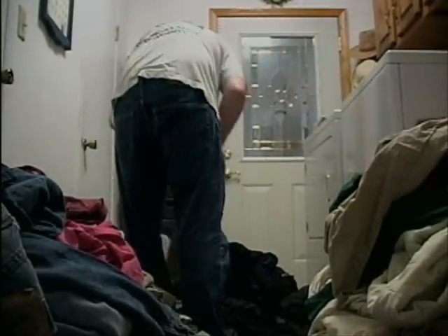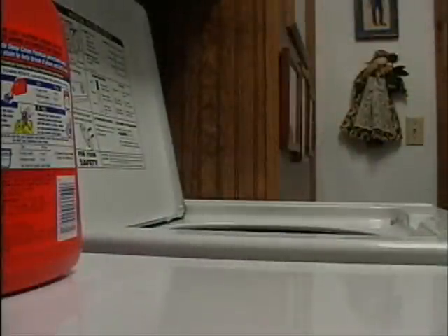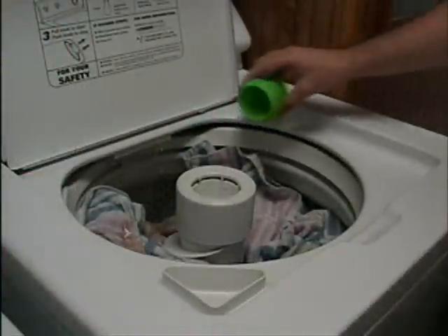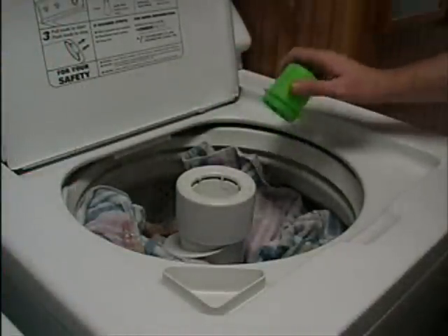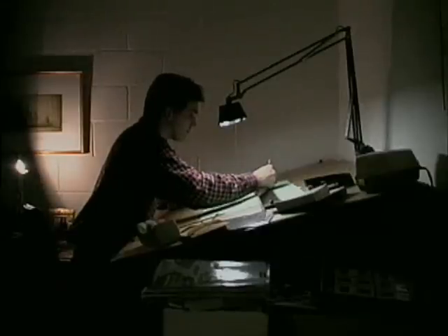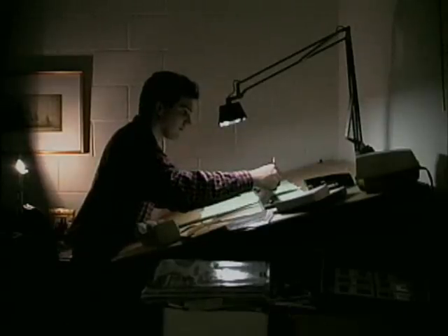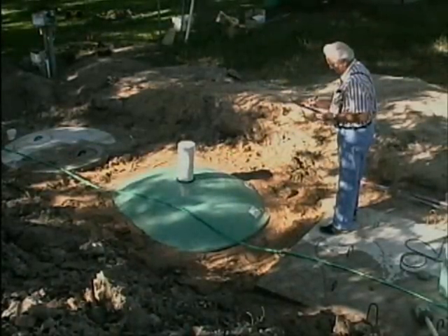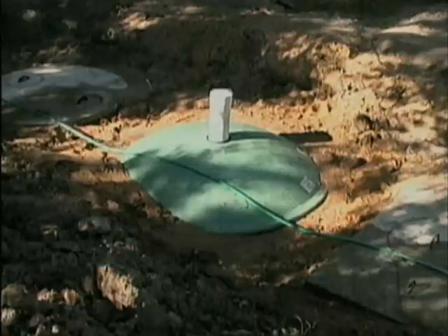For example, doing all the laundry on one day causes a high flow rate that can impact the system. It is important to evaluate this and similar resident habits to get an accurate estimate of wastewater discharge. Design and placement of the drip field requires a number of special considerations. The pretreatment and land application components are then selected and matched, both to each other and the site.